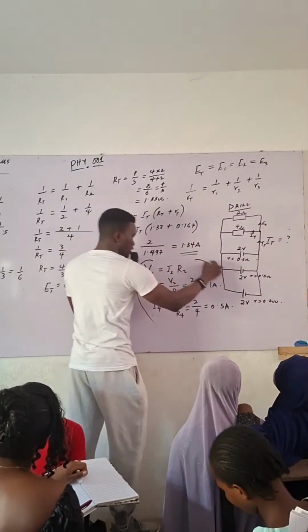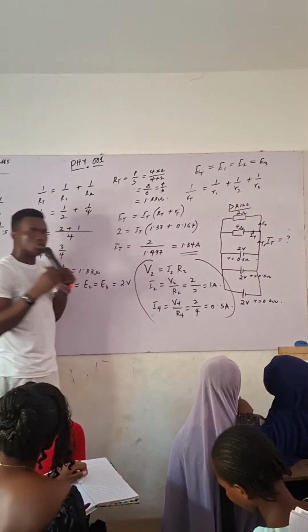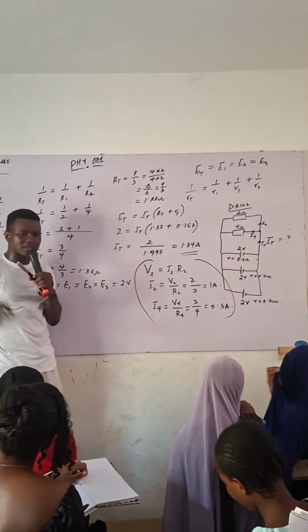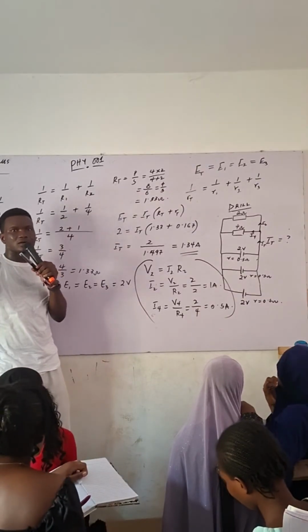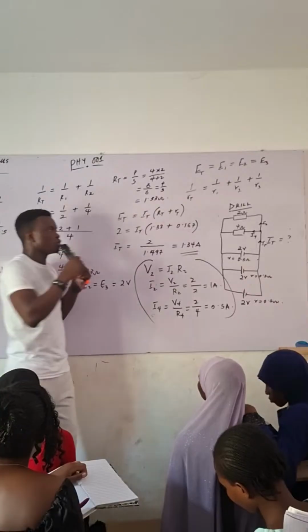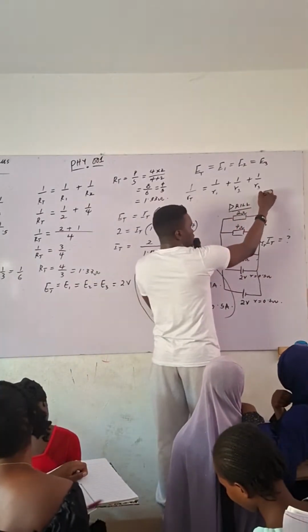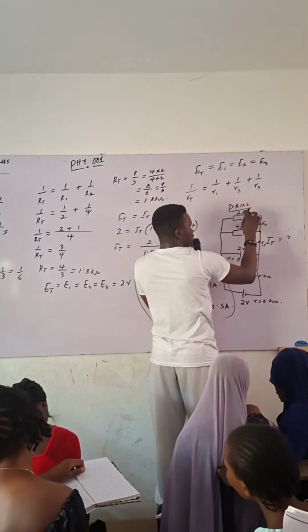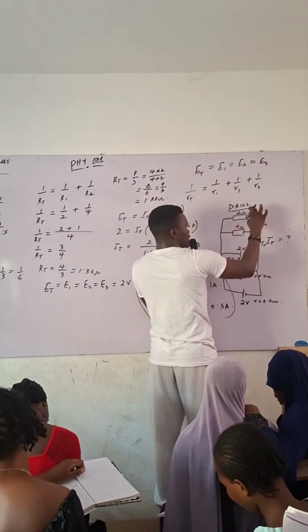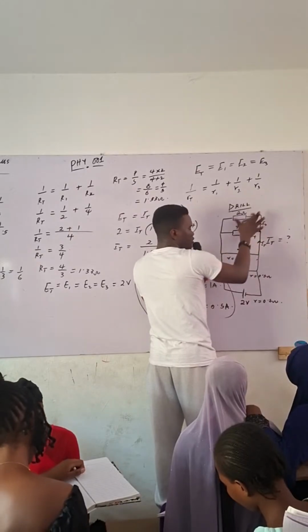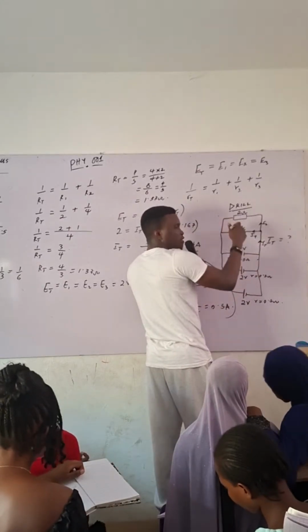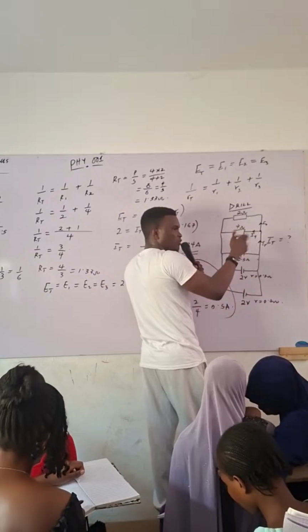So there's something that is probably wrong due to the internal resistance. Except that we still want to treat them like, if I'm looking for the current through this, I can now say, neglect this one. When you have a complex circuit like this, we actually use Kirchhoff's law to get the individual currents.